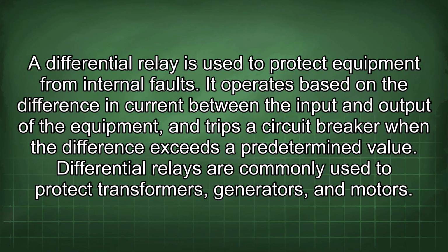A differential relay is used to protect equipment from internal faults. It operates based on the difference in current between the input and output of the equipment and trips a circuit breaker when the difference exceeds a predetermined value. Differential relays are commonly used to protect transformers, generators, and motors.